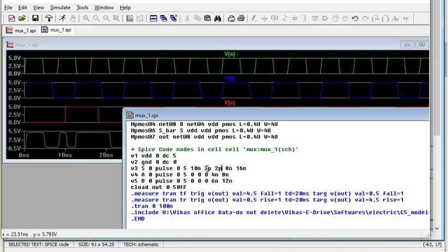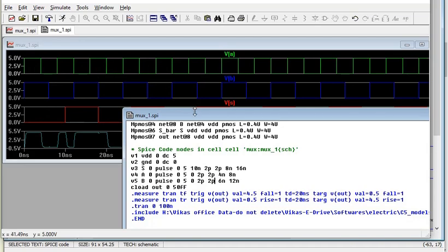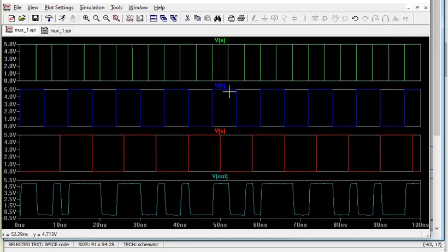In fact, when I use 0, it will automatically take some random value of rise time, but when I use some value in picoseconds, it is going to give me an exact square pulse. So I can incorporate rise time and fall time like 2 pico for all my signals. To give you an idealistic view of this pulse in terms of its square shape, everywhere I give 2 picosecond of rise time and fall time, save it and run it. All the pulses are square, and accordingly your output will be the same.